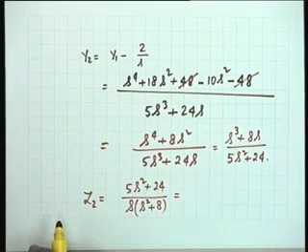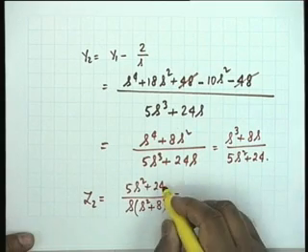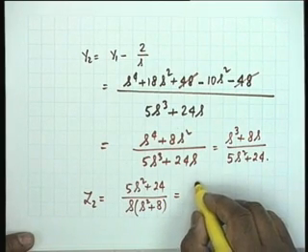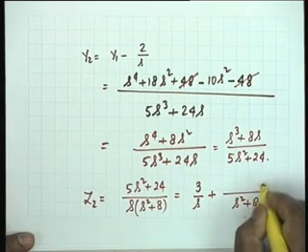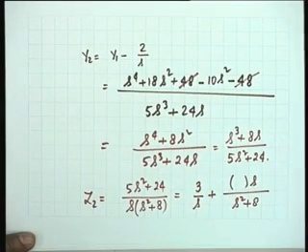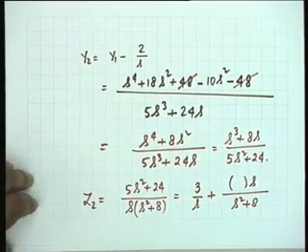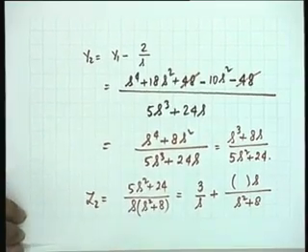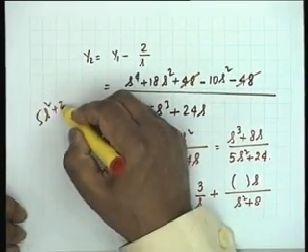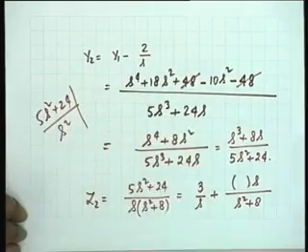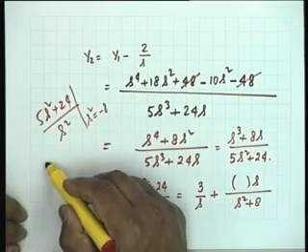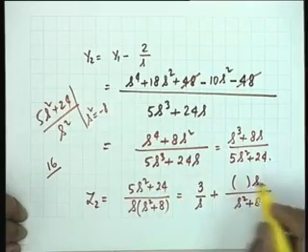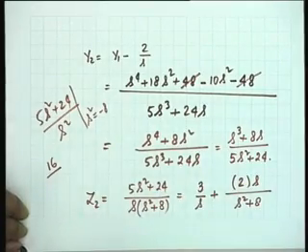There is indeed a pole at the origin which will take account of the capacitor C3, and that pole, what is the residue? 3 by s, plus what you will have here is s square plus 8, then s and a constant. What is this constant? It is 5s square plus 24 divided by s squared, with s squared equal to minus 8. So, 16 divided by 8, that is 2.